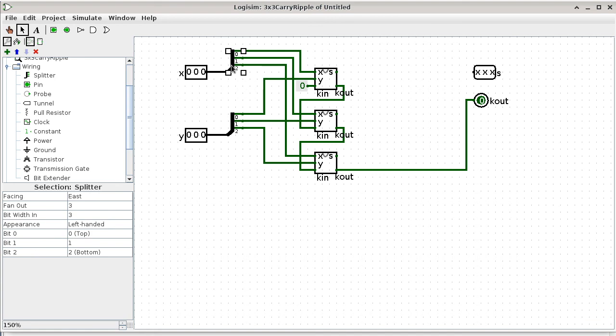You take a splitter and flip it around, exactly. There are several ways to flip it around depending on how you want it to look. So you can go to the property and say face west first. So now the split end is to the left, and the merged end is to the right. Okay, so that is sufficient for us already.